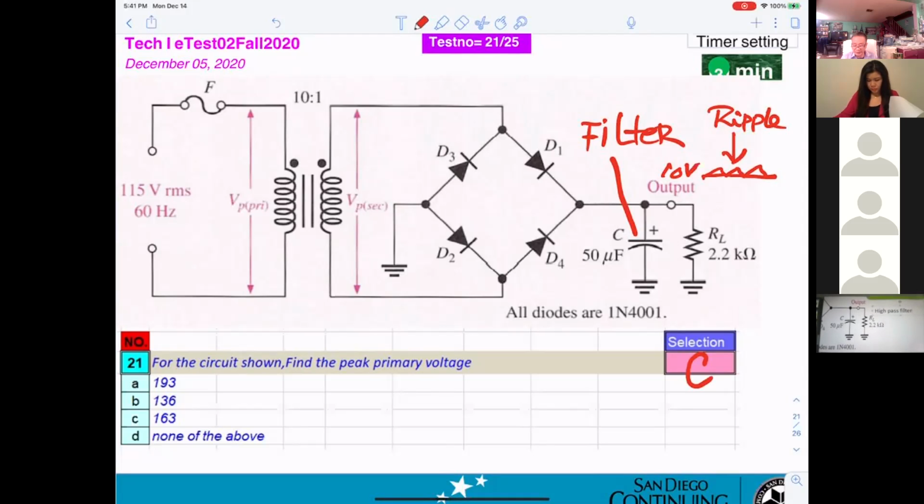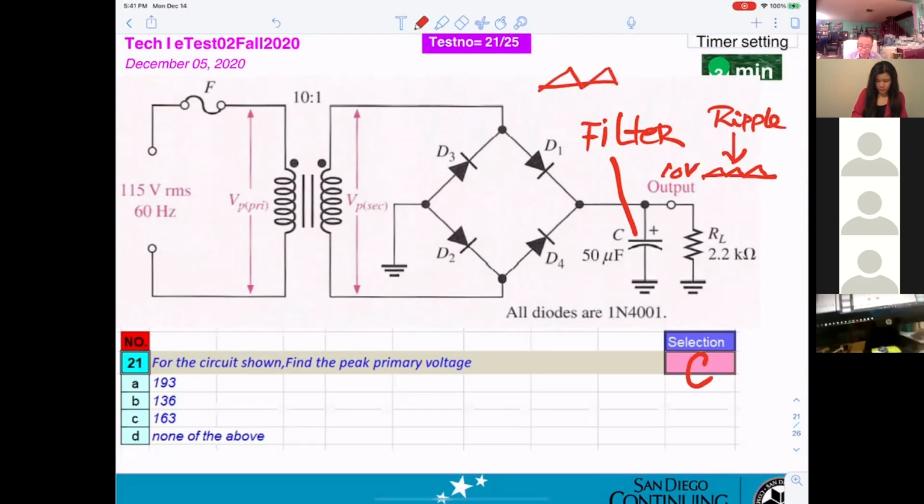So that's why you can get a ripple. If you want a small ripple, then the capacitor value will be small or bigger? The bigger the capacitor, the less noise. Exactly. Otherwise, at the output, you can get a very big ripple. That is not good. A big noise.